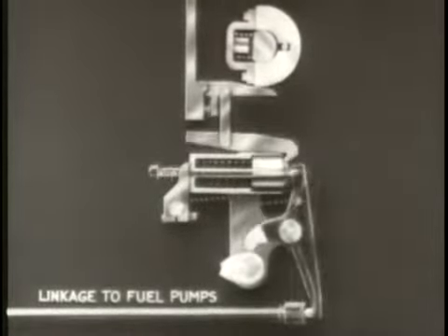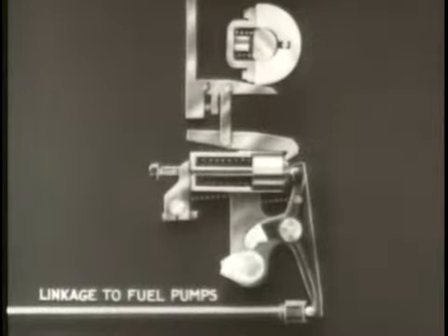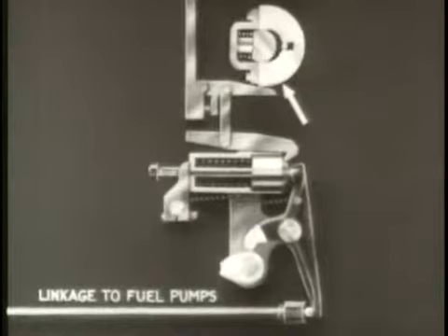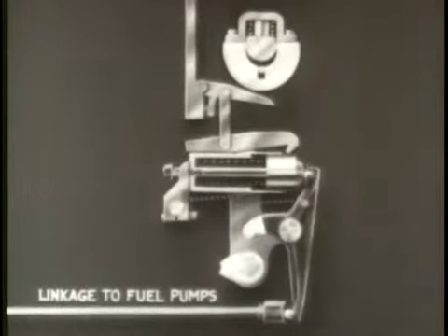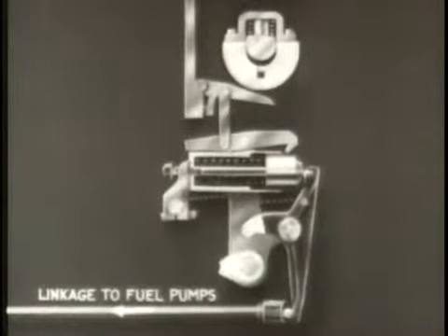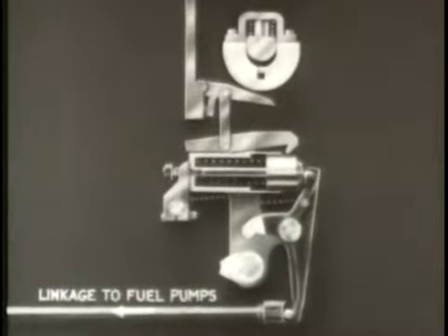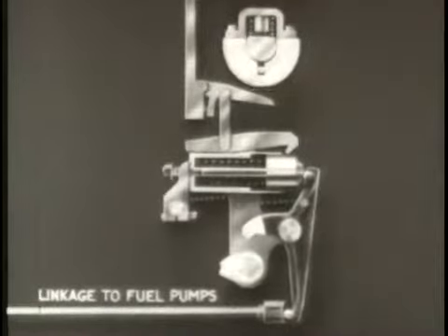Let us repeat the action of this mechanism step by step. The flyweight is held to the drive shaft by a spring. When the engine overspeeds, centrifugal force overcomes the resistance of this spring, and the flyweight moves away from the shaft. In this position, the rotating flyweight trips the latch, which releases the spring-loaded plunger. The plunger pushes against the fuel cutout lever, which in turn moves the fuel pump control to the no injection position, and the engine stops.